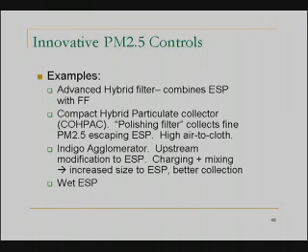Another example of an innovative technology is the Indigo agglomerator, which is basically an upstream modification to an ESP, which applies an upstream charge to increase the particle size before it sees the ESP, therefore allowing that ESP to do a better job at collecting particles. Certainly another example is a wet electrostatic precipitator.